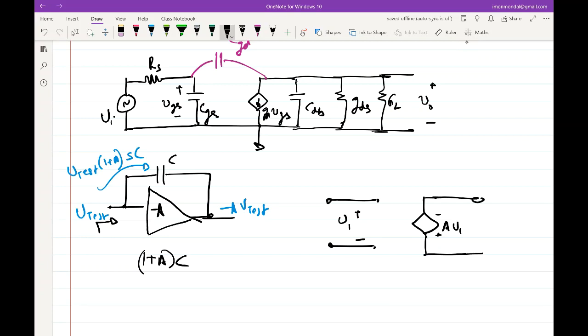And it has a zero output impedance, which means that whatever I connect here, or between this and another terminal, the voltage at the other side of the voltage controlled voltage source will not change, right? So the implication of that is what is the Miller effect, the increase of capacitances.